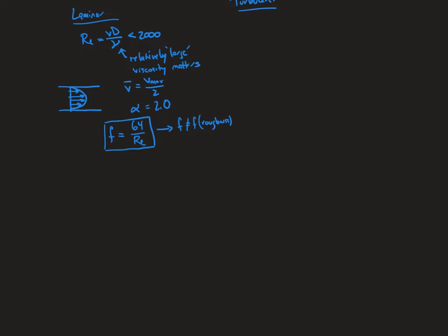So Darcy-Weisbach is hf equals f L on D, V squared on 2g. Okay, we can plug this guy in. hf equals 64 over, in this case, I'm going to plug in the Reynolds number, and I'm going to leave that for one second, L on D, V squared on 2g. And let's go ahead and plug in this Reynolds number as rho V D on mu.